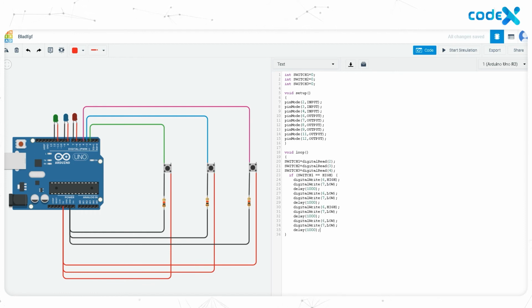The blue LED is connected to pins D8 and D9. So change the pin numbers to 8 and 9. Similarly, to turn on the green LED, paste the same syntax to turn the LED on or off in the next line. Change the pin numbers to 11 and 12.